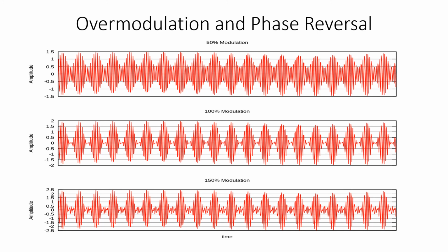So what is percentage modulation? It is the maximum of |ka m(t)|. If it is equal to 0.5, you can see a very clearly defined envelope. There is no distortion. In this case, the message is considered to be a low frequency sinusoid.